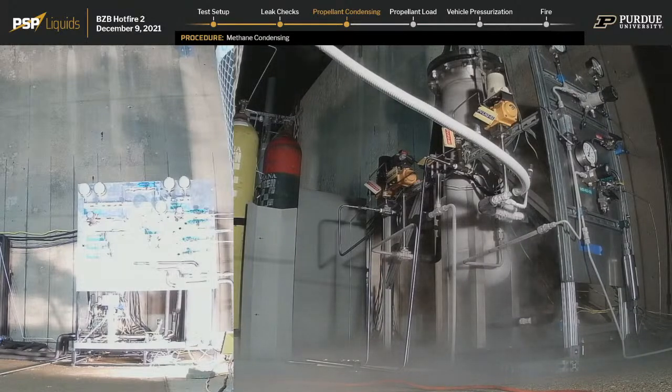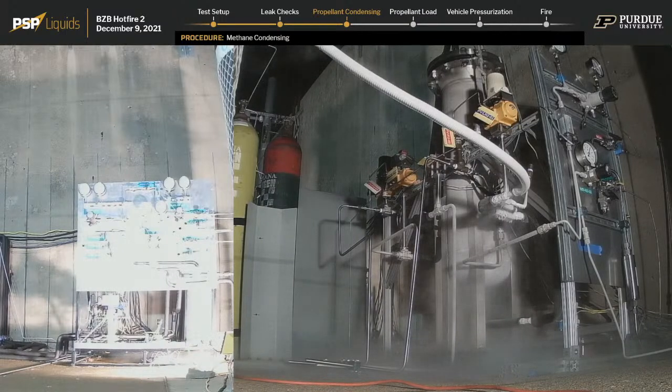Right. Yeah, and we're actually venting, hopefully at this point, liquid. And it's actually instantly evaporating? Vaporizing, yeah. That's the right word. Not sublimating because it's not a solid. But it's instantly vaporizing into the gaseous form, and that's why you see so much gas coming out of such a short system. I believe you can even tell which vent line is coming out because that's the one that is frozen.